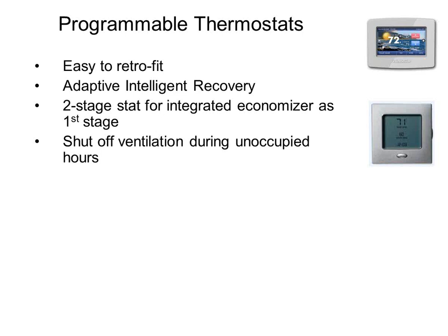Super easy to do. If you're looking for specific thermostats that do it, we created a list of them and put them on the FAQ section for the Focus on Energy Wisconsin rebate program. So there's a bunch of them listed on there, and I got it set up so you can see the model number of the thermostat, you can see the terminals you got to wire to, and the settings you got to change on the stat to make it happen. If you can't find that list on their website, you want me just to send it to you, that is fine. Also, I can do that.